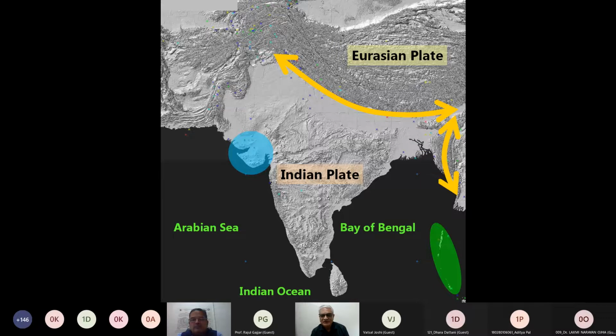Of course, there are surprise earthquakes in the Indian plate, but this is the known danger and we have to protect ourselves from that. 200 kilometers from these locations are still under the radar of damageability, which means that if you have an earthquake in Bhuj and Ahmedabad is 225 kilometers away, you will have damage there. And if you have an earthquake in Himalayas, and any of the towns like Delhi are only 200 kilometers away, radial distance, then you should be able to prepare yourself for such damage.